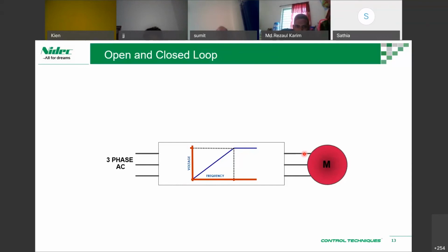Okay, so when we talk about VFD, from a manufacturer point of view, variable frequency drive, we are controlling the frequency. But from an end use point, it's a VSD, variable speed drive. So what you see is the speed is being controlled, so you get a variable speed. But from a manufacturer point of view, it's variable frequency. So we just change the frequency, and on the other end, the speed changes.